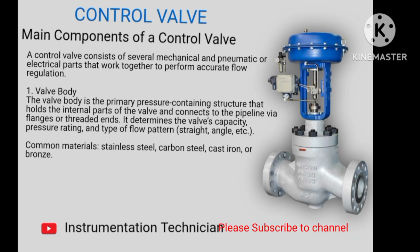Main components of a control valve. A control valve consists of several mechanical and pneumatic or electrical parts that work together to perform accurate flow regulation. 1. Valve body. The valve body is the primary pressure-containing structure that holds the internal parts of the valve and connects to the pipeline via flanges or threaded ends. It determines the valve's capacity, pressure rating, and type of flow pattern, straight, angle, etc. Common materials: stainless steel, carbon steel, cast iron, or bronze.